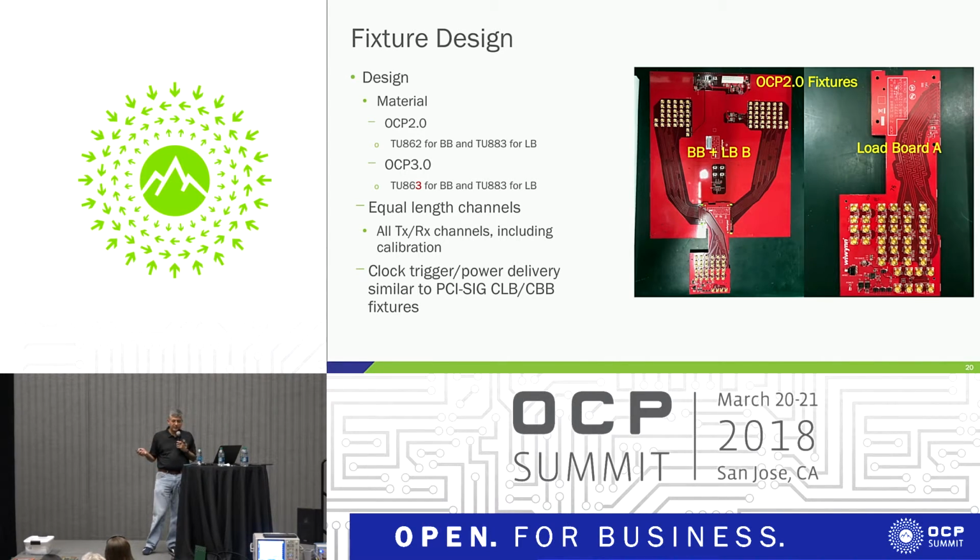The other aspect is that all the transmit and receive channels are equal length. We designed these such that they all match within 1% of each other, mostly to help us with designing the calibration board. Now in the calibration board, we can design for just 1 channel, so we don't have to worry about calibrating each and every channel independently, since all these channels are matched within 1% of each other.